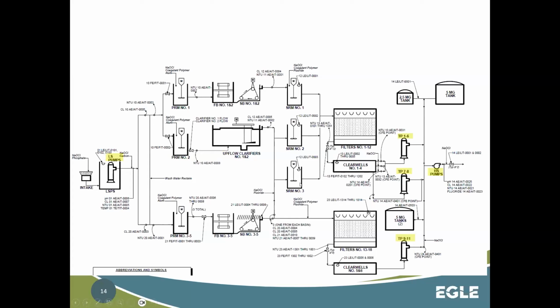So then we go to our secondary, like we were speaking about, more the coagulation, flocculation, settlement. Then we go to our filters, right? And so that once we enter our filters, we go to our filter beds, finished water is filtered out into the clear wells.